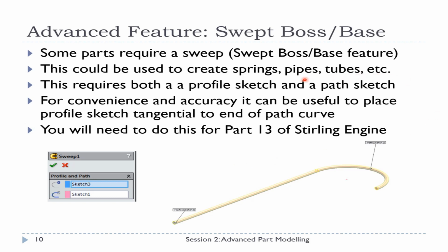If you think of each of these design elements, they all have a constant cross section, but their extrusion direction is not linear. It's basically a route. So we can implement this method using the sweep feature.